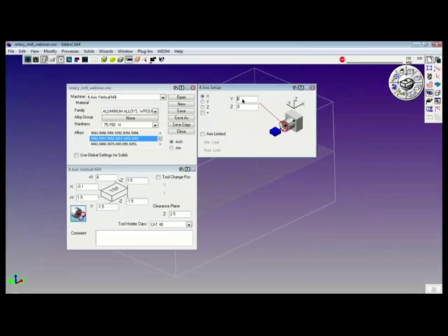The Y and the Z input boxes determine the center of rotation for this particular rotary axis. Y0, Z0 establishes the center of rotation at the center of the rotary axis. When setting up the tools on the machine, the Z offsets have to reflect the distance from Z0 to the center of rotation. All of the depth values are positive from the center line up.